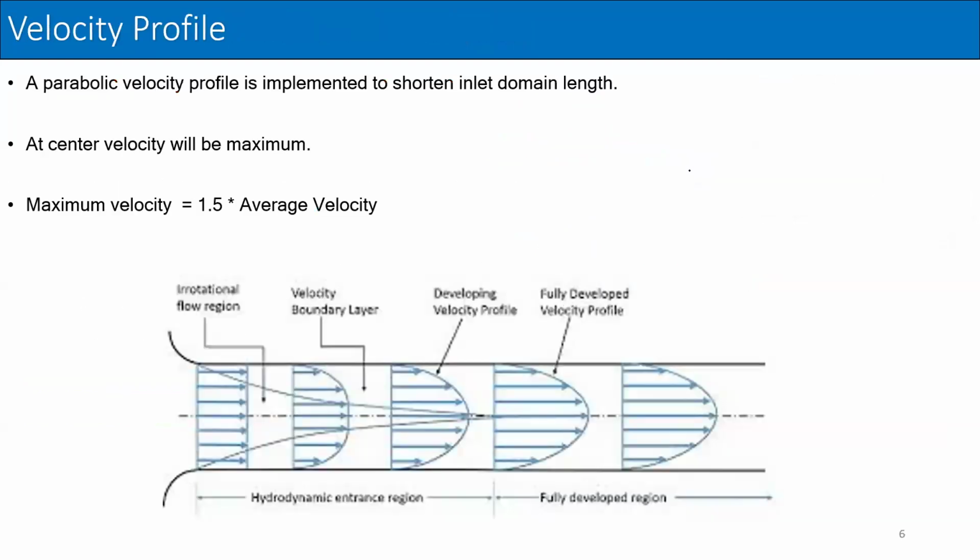So now let's go further. To apply the velocity profile in laminar flow in the channel, the velocity profile is parabolic. In pipe flows, the maximum velocity is equal to twice your average velocity or mean velocity. That is the average of all these velocities. But for the channel case, you can read some good fluid mechanics books. The u maximum is equal to 1.5 times the u average or u mean. So we use this value.